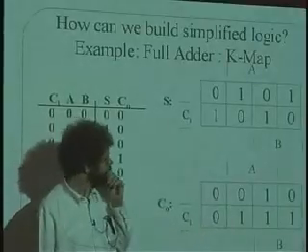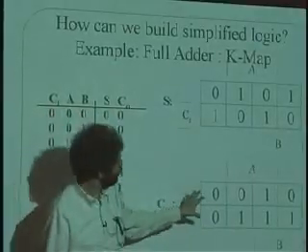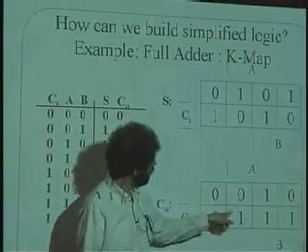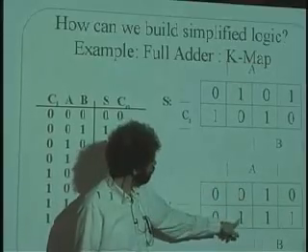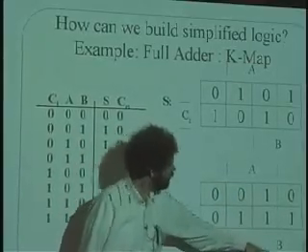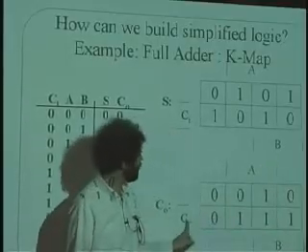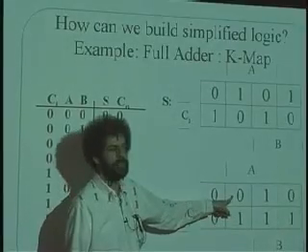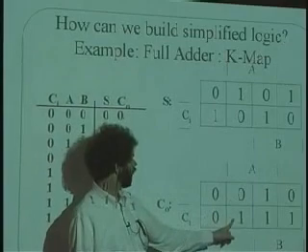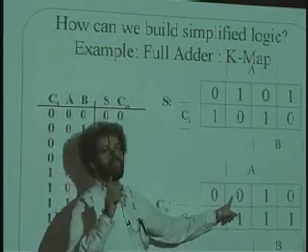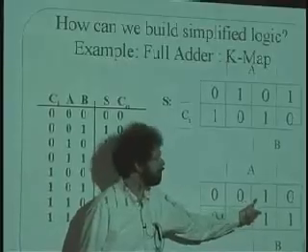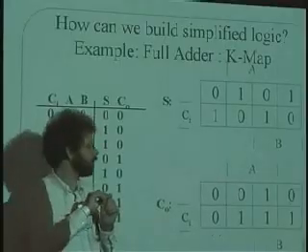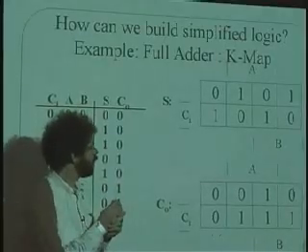That's pretty neat too. Now what's the characteristic that a checkerboard like this has? Well, it has an amazing thing. First of all, if I'm in any square, this corresponds to A equals 1, B equals 0, because I'm not in the 2 columns with B, and C sub I equals 1. That's this place here. If I move in this direction, how many of the input bits change? I go from here to here. Only 1. If I go from here to here, how many change? 1. Here to here, 1.